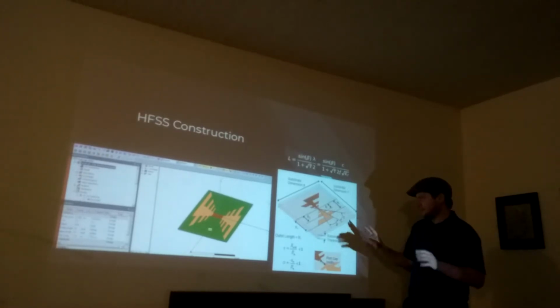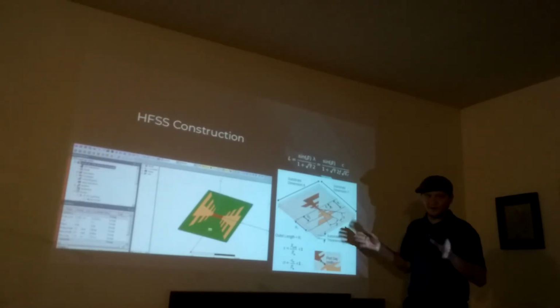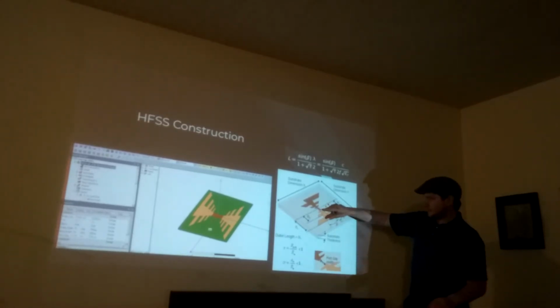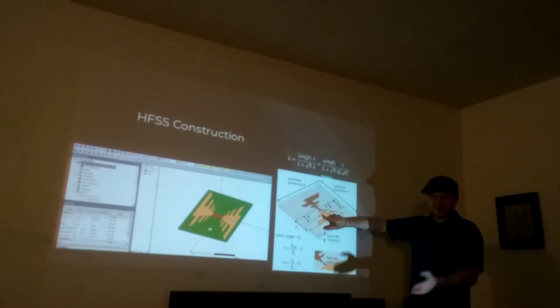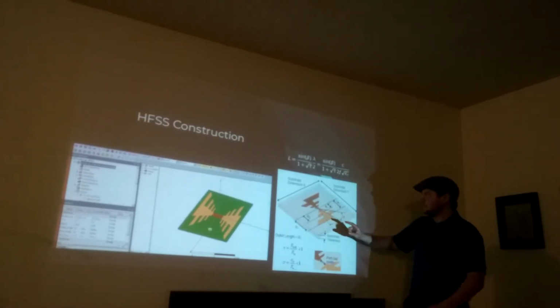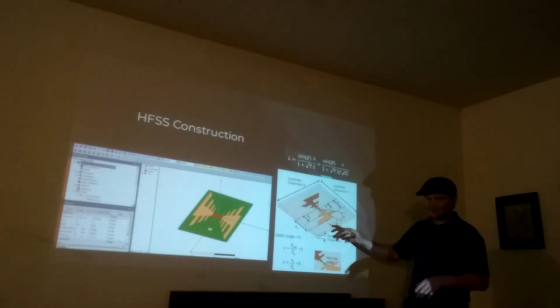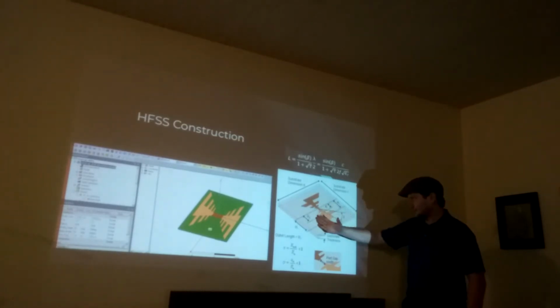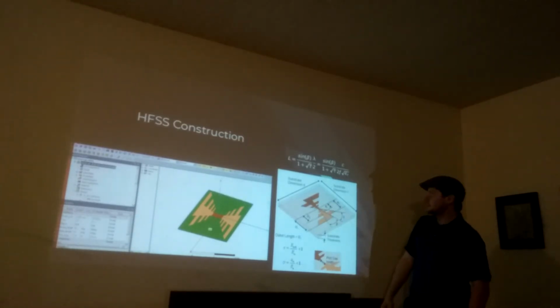Now, I didn't have time to test it, but I think if you want your antenna to work specifically at 2.4 and 5 gigahertz, which is what I was designing for, you could just cut off the corresponding teeth that you don't need in order to hit those frequencies. And you'll still retain the nice properties that we were discussing before, because it has that nice periodic scaling property to the power of phi.